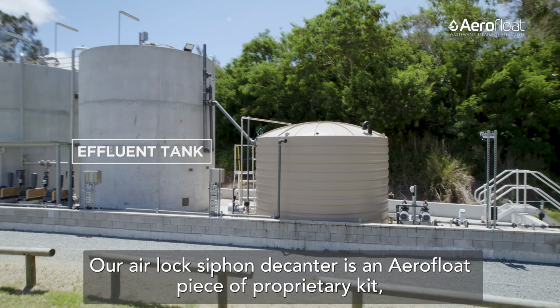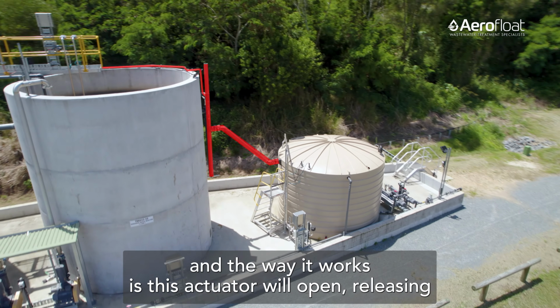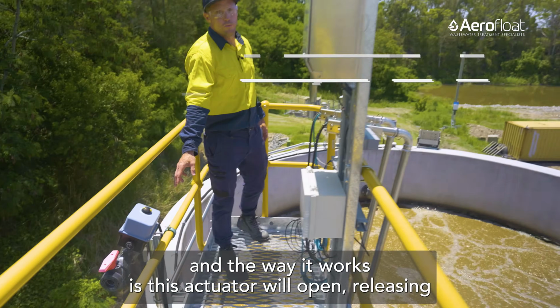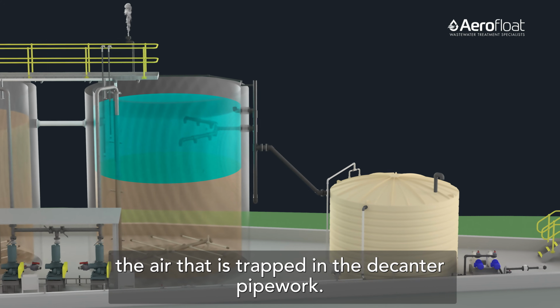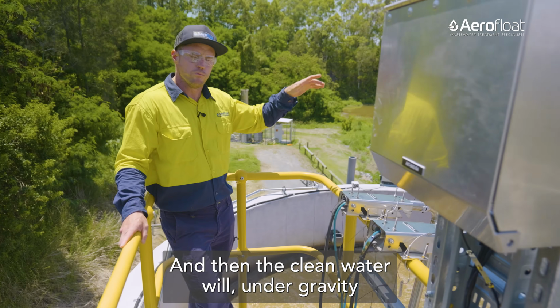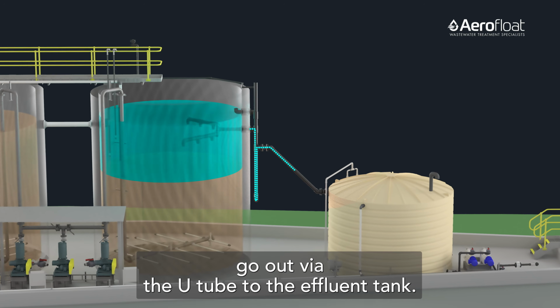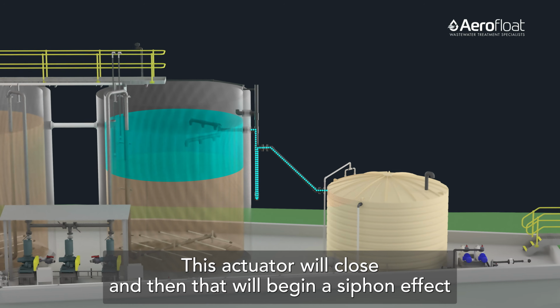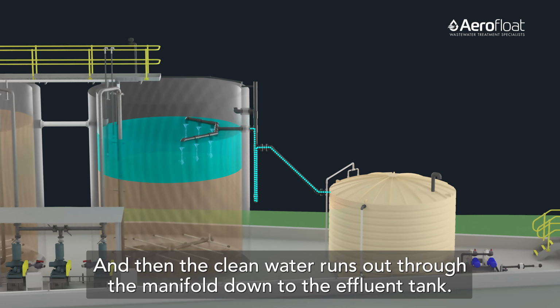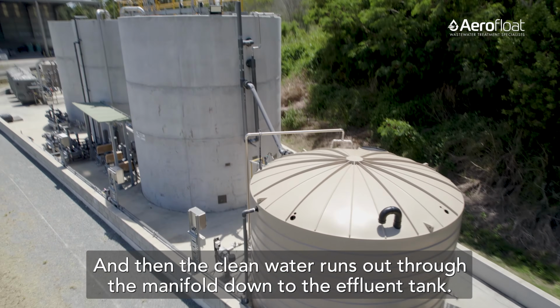Our airlock siphon decanter is an Aerofloat piece of proprietary kit, and the way it works is this actuator will open, releasing the air that is trapped in the decanter pipework, and then the clean water will, under gravity, go out via the U-tube to the effluent tank. This actuator will close, and then that will begin a siphon effect. The clean water runs out through the manifold down to the effluent tank.